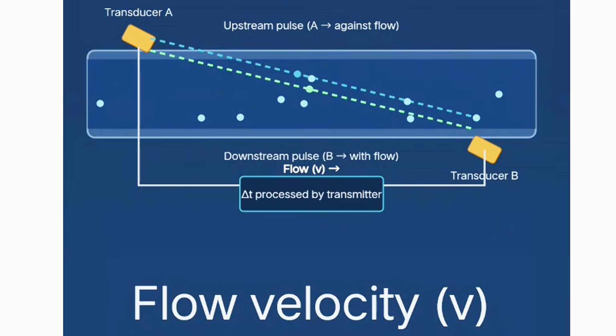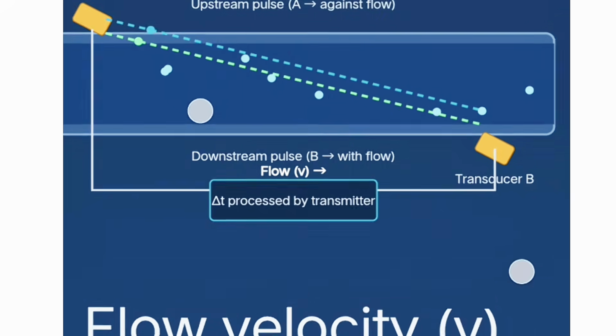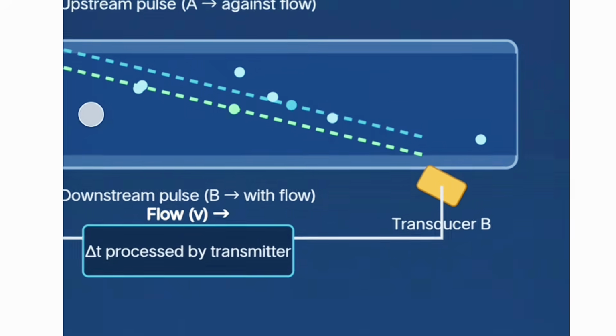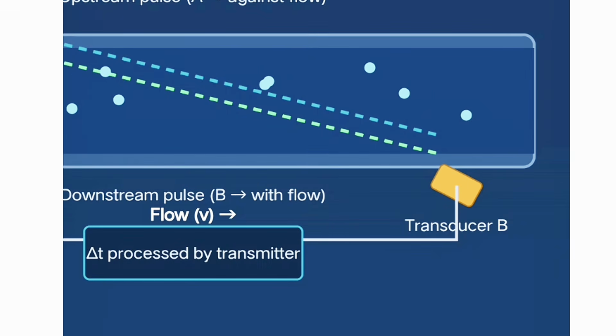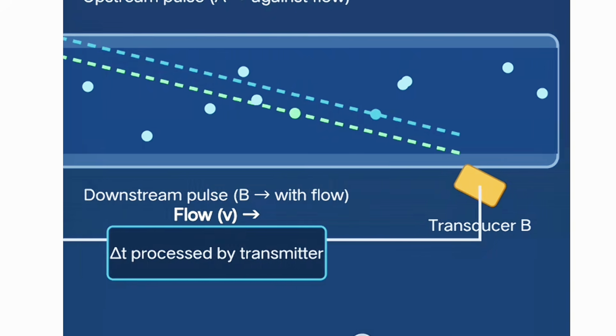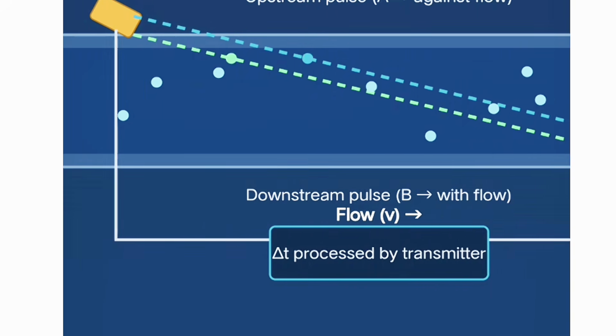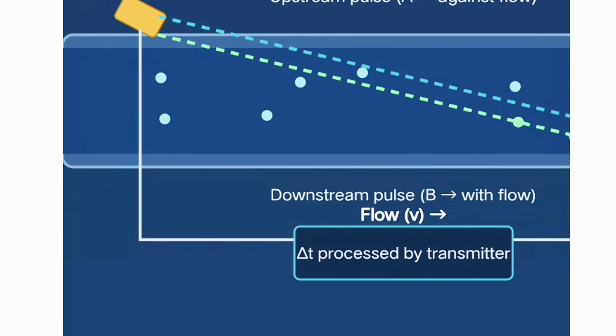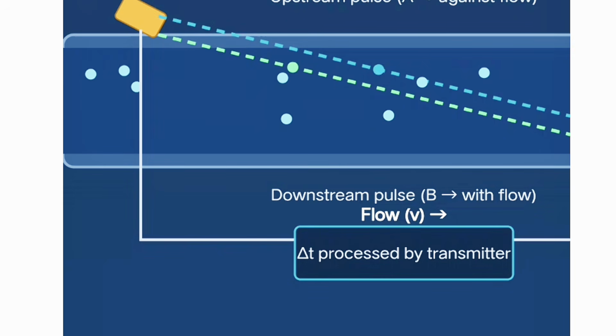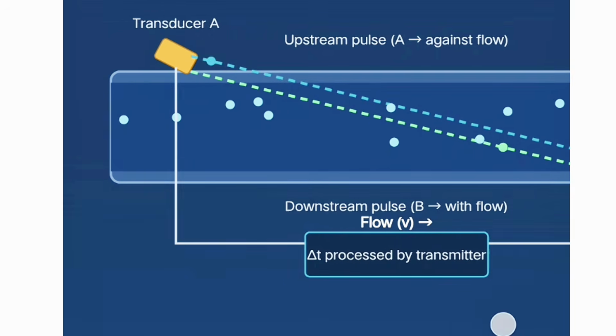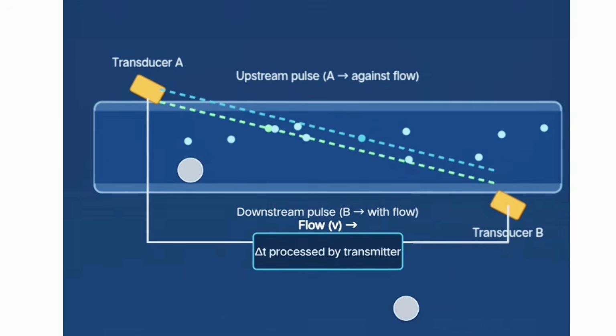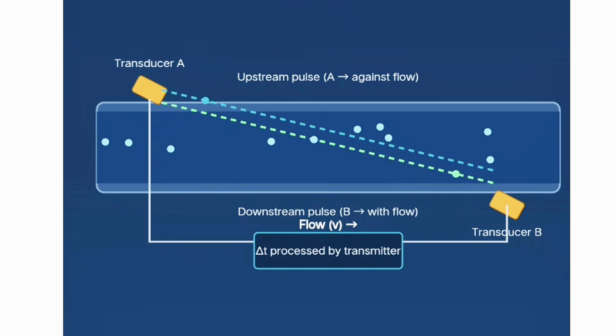Why this matters. Ultrasonic transit time flow meters are used where a mag meter cannot be, on non-conductive liquids, oils, and lines where a clamp-on, non-intrusive sensor is preferred. Unlike mag meters, they measure flow using the speed of sound through the liquid rather than induced voltage. Knowing this principle helps distinguish a genuine no-flow condition from a poor signal or weak coupling fault during troubleshooting.